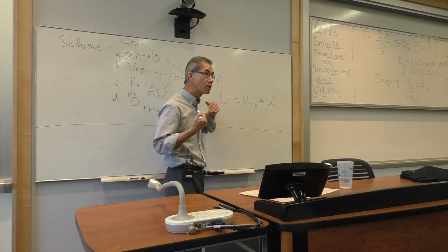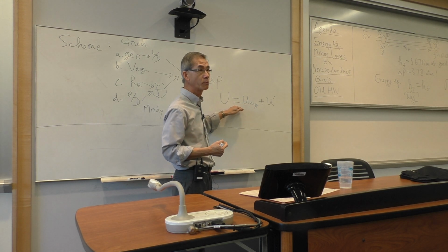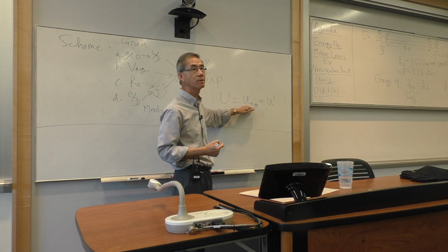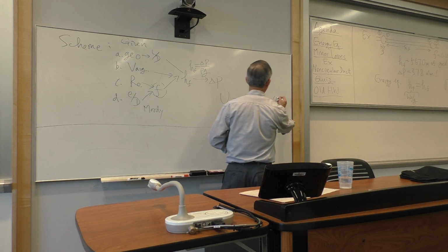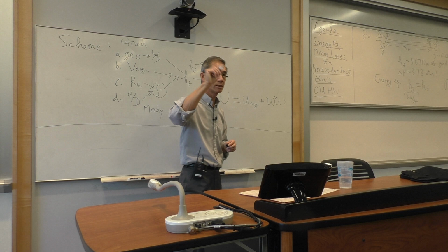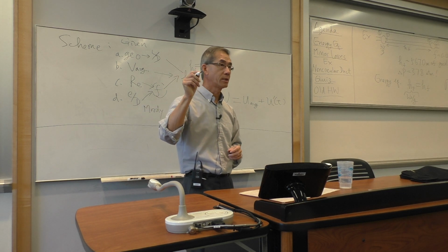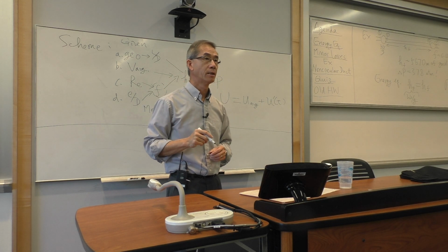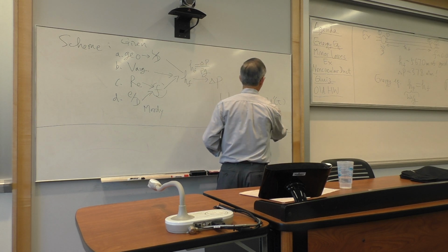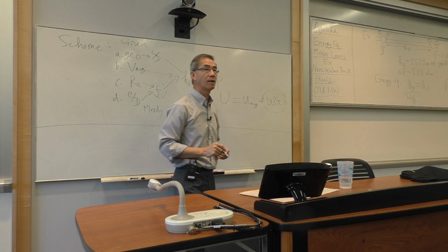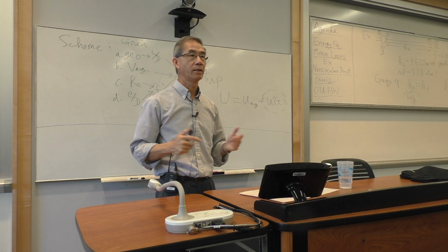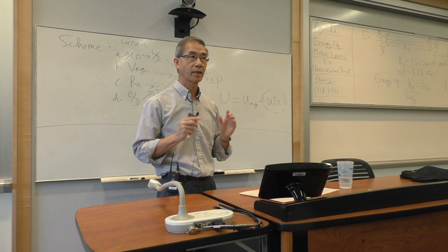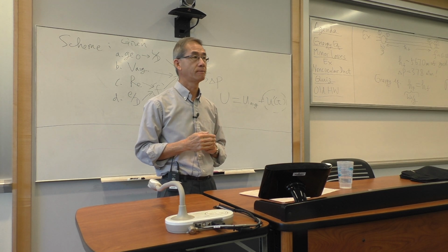All the velocity that we talk about in this context has to be broken down into a mean component, a steady component, and a fluctuating component that's highly time dependent. Because turbulence is just dancing around, maybe in the kilohertz frequency range, and the equation of motion is not capable of including this time dependent term. And everything becomes purely experimentation. The equation cannot be solved exactly.